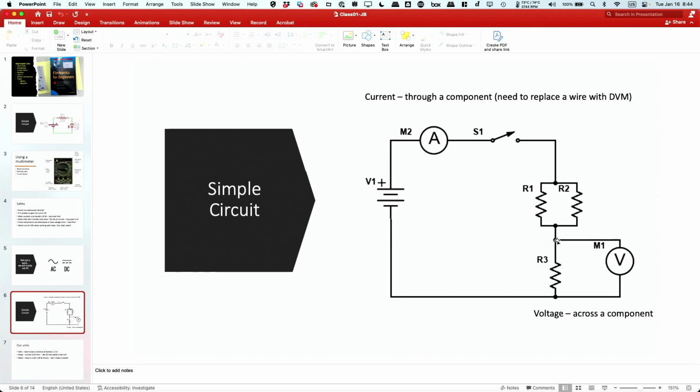So is that voltmeter going to read more or less than the voltage of the battery? We got one vote for less, one vote for the same. Less. So what about the ammeter? Is it going to read the entire current flowing through the battery or not? Yeah, so it'll read all the current, right? Because the current had no other choice than to flow through the ammeter. There was not another path for it.